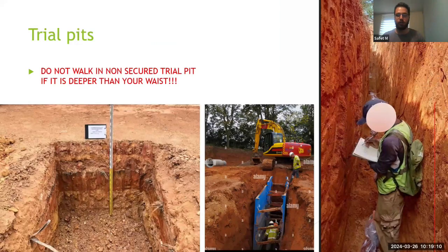So generally, trial pits, as you all know, can be excavated manually, or you would mostly do it with the excavator. The one important thing about trial pits: do not walk inside if it's unprotected. As you can see on the right side, there's one guy in a trench in a cohesive or not cohesive soil. It looks like sandstone.